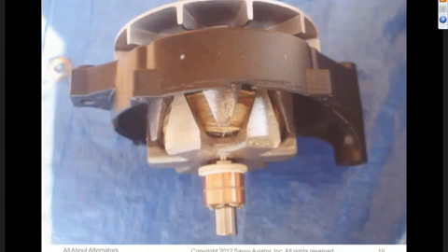Here is a rotor mounted to the non-drive end cap of an alternator. You can see the slip rings on the bottom there, and you can also see a fan that's mounted on the opposite end of the shaft. Most alternators have some sort of a fan, either external or internal to the alternator, that blows cooling air over the silicon diodes in the rectifier assembly, because like most high power solid state things, those rectifiers put out quite a lot of heat, and they need to get cooling air.